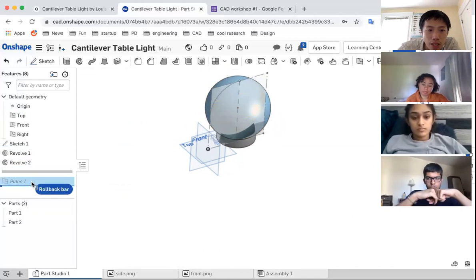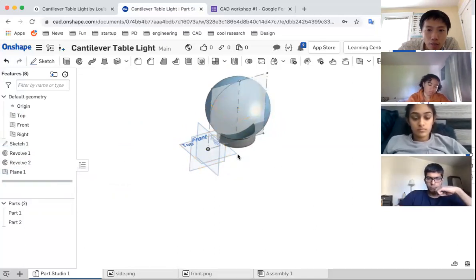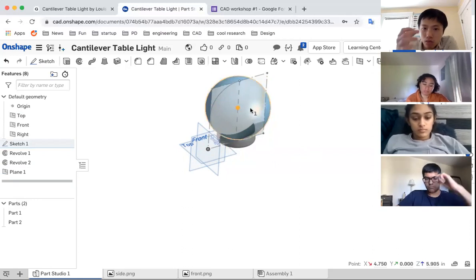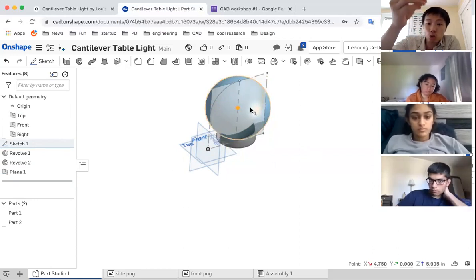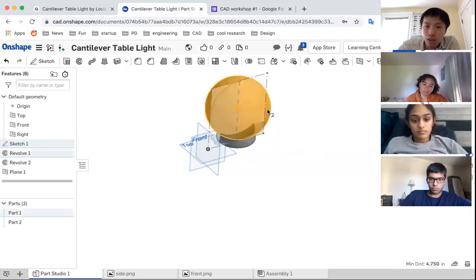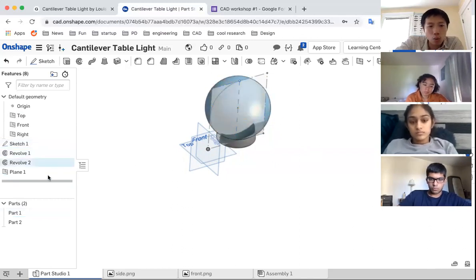That plane that we just created is exactly where we want it. It's parallel to the top plane, and it's exact, and it's right here, right? And the vision is that I'm gonna draw a circle there and then extrude it down to create that base, and I'm gonna add that cylinder to this material so that it's one piece. So ultimately, it's one part. So let's do that. By the way, one thing I just kind of did on the left.